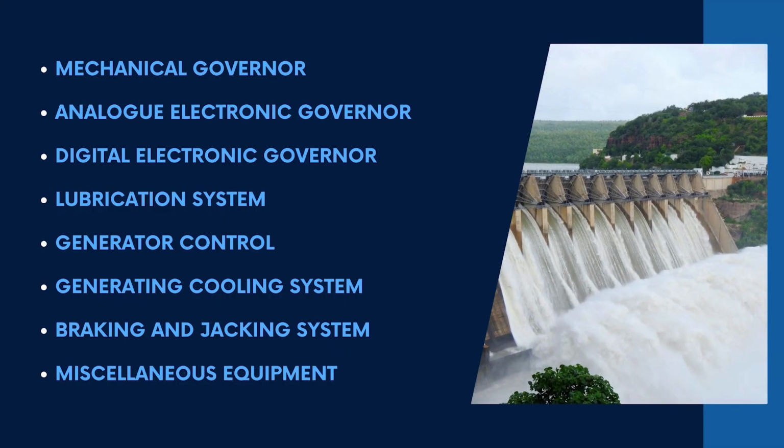When the water head is high, it is more economical to pump from the tail race or draft tube. Each turbine may have its own pump, generally with one standby common to all units. In small hydro, cooling water is sometimes pumped from underground by a submerged pump to avoid an elaborate treatment plant for cleaning water. Now, let us talk about the braking and jacking system.